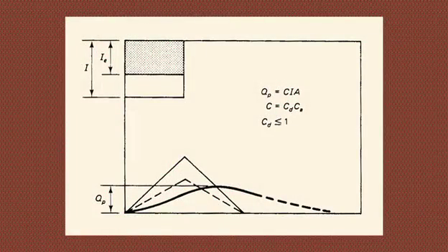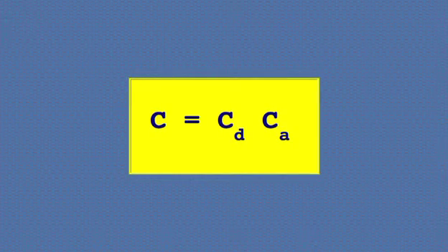This situation is applicable in catchments of very mild slope, say less than 0.0001. Diffusion increases the recession time and reduces the peak flow. Thus, a hydrograph cannot be obtained solely from the mass balance. The reduction in runoff coefficient to account for diffusion leads to an expression where C sub D is less than 1.